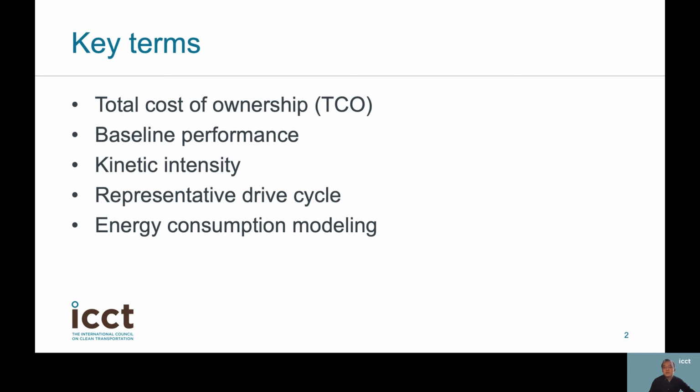Finally, energy consumption modeling is a step in the fleet-wide planning process where we plug in the drive cycle information of a particular route and the technical parameters of soot-free and zero-emission buses into vehicle simulation software. It is a key determinant of the total cost of ownership and a very useful way to compare technologies and operational strategies to review which technology will perform best and at the lowest cost.